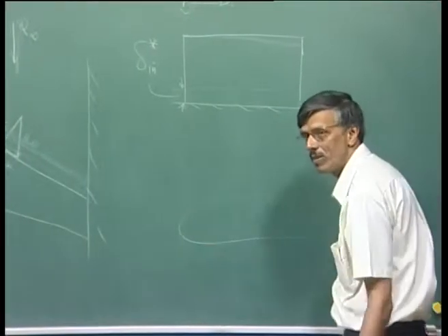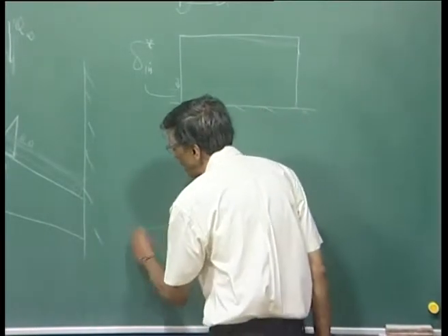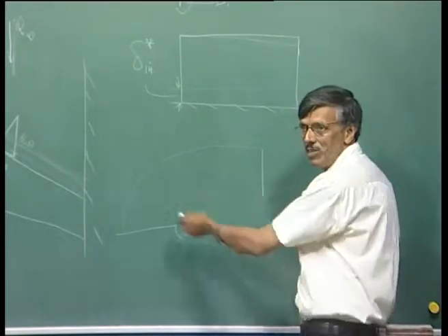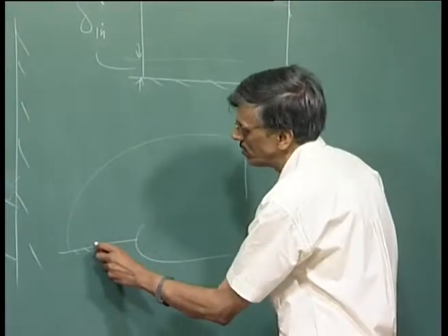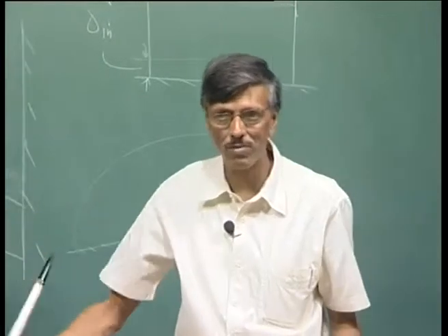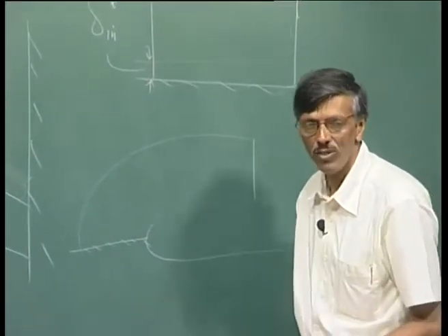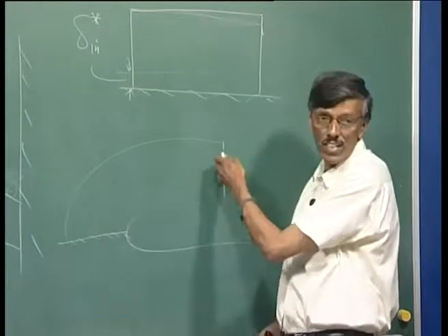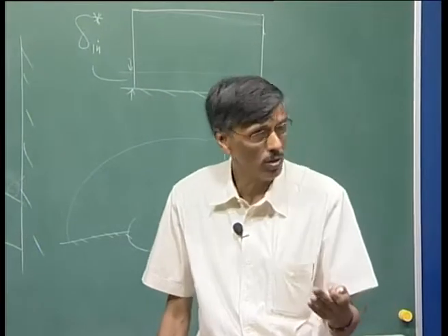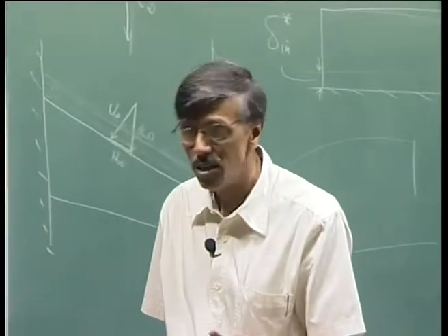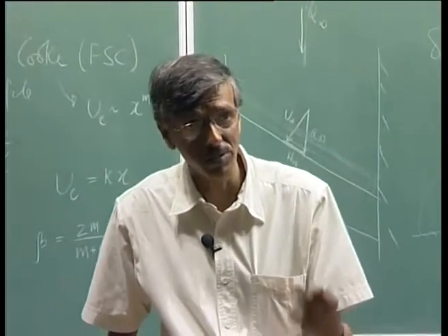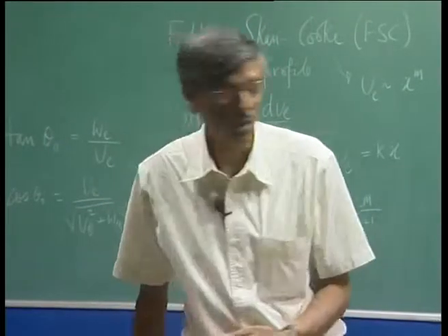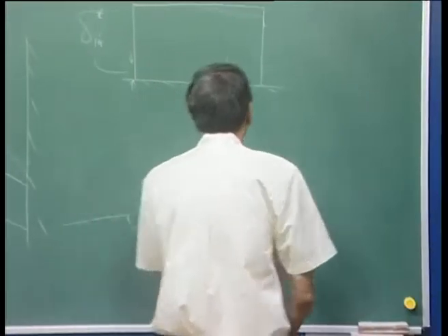Let's say this is the leading edge of the wing and this is my attachment line plane. So now what I could do is basically study the instability over the wing. This solution as a function of time can come from what we have done just now, right? So it's like creating your inflow condition, and then you can study that. You recall this is what we talked about, the necessity for first seeing what happens on the attachment line and then subsequently what is its effect downstream on the wing. So that part of the investigation is overdue.